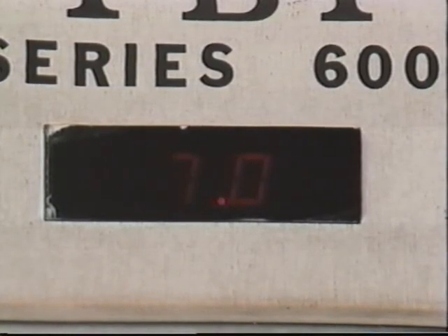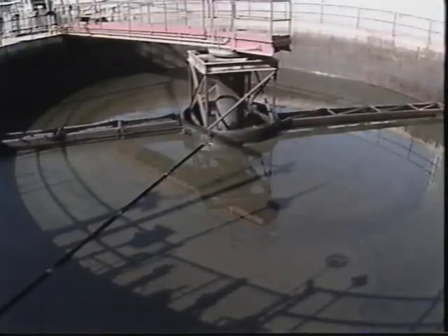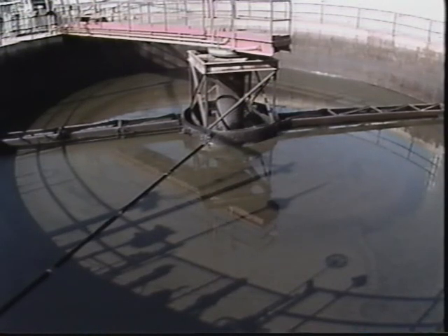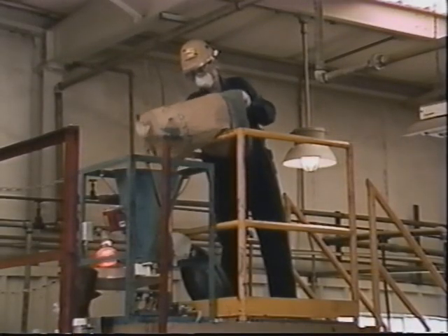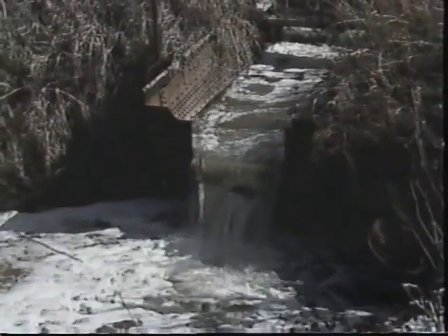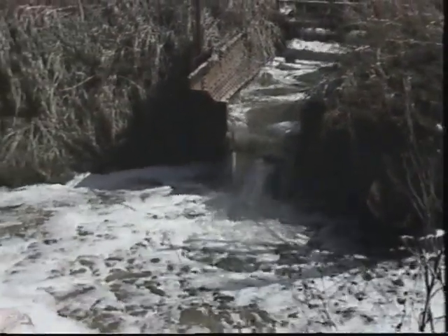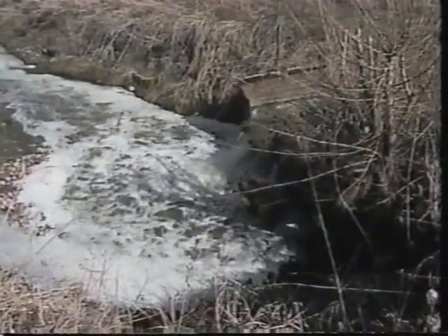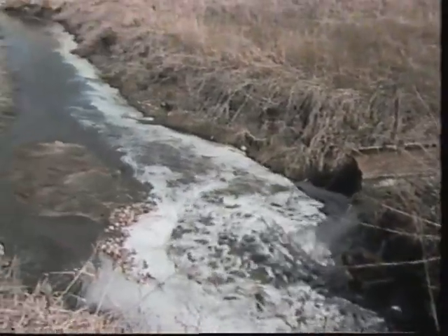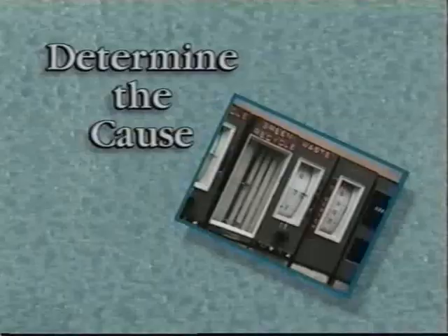The pH level should be near neutral before the water can be safely discharged. A high sludge blanket level in an upstream clarifier can affect the pH level, so the pH may have to be adjusted to make sure the water can be sent on. In extreme cases, discharge to the environment may have to be stopped entirely, and the wastewater would be recycled through the treatment system until the problem was taken care of.